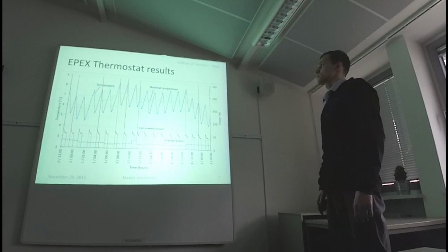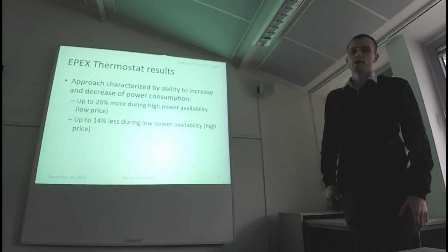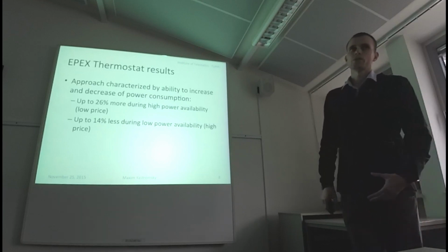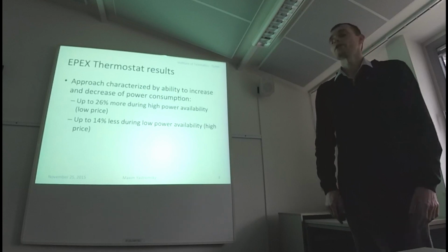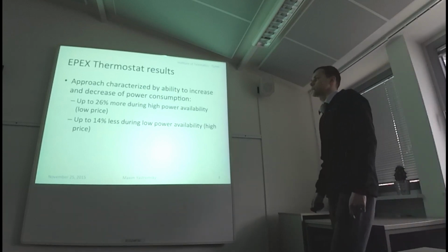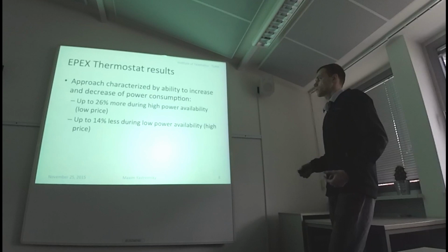So what do these results say? This approach can be characterized by the ability to increase or decrease the power consumption of the refrigerator. For example, during high power availability times, the power consumption can be increased up to 26%, and during low power availability, in other words high price, the power consumption can be reduced up to 14%.